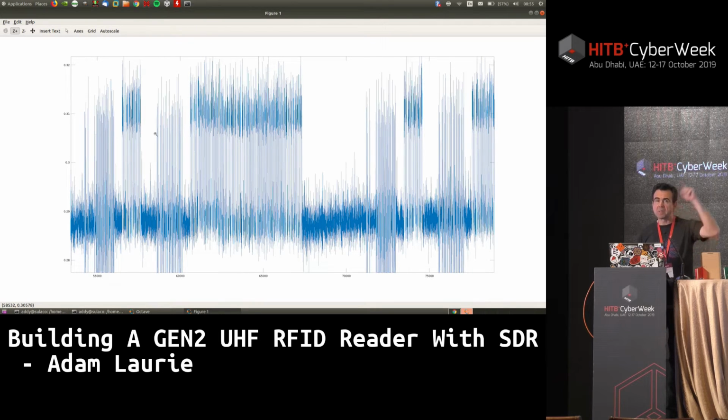And actually, if you go way back to the original project that this research is based on, there's a note from the author saying he had to rewrite the GNU Radio USB handling routines to take out all the USB buffering so it ran in nearly real time in order to get this gap right. As soon as I saw that, I looked at LibBladeRF, and you can just set the number of buffers to 2, I think, is the minimum. And I did that, and bingo, it just worked.